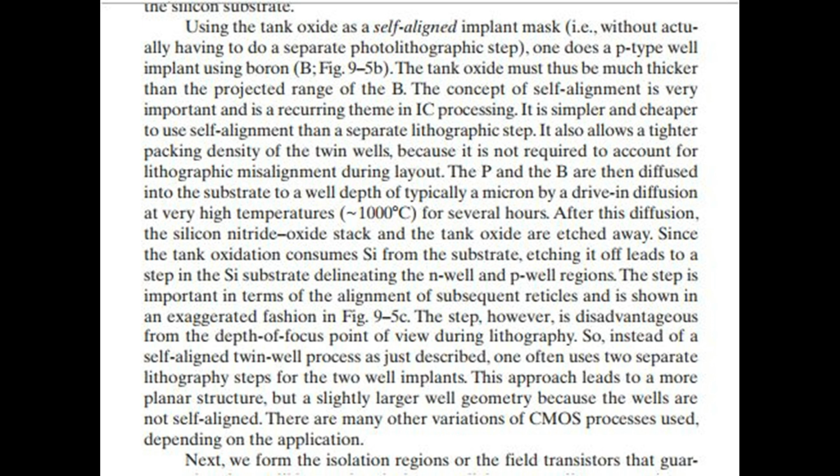The concept of self-alignment is very important and is a recurring theme in integrated circuit processing. It is simpler and cheaper to use self-alignment than a separate lithographic step. It also allows a tighter packing density of the twin wells, because it is not required to account for lithographic misalignment during layout. The phosphorus and the boron are then diffused into the substrate to a well depth of typically a micron by a drive-in diffusion at very high temperatures, 1000 degrees Celsius, for several hours.